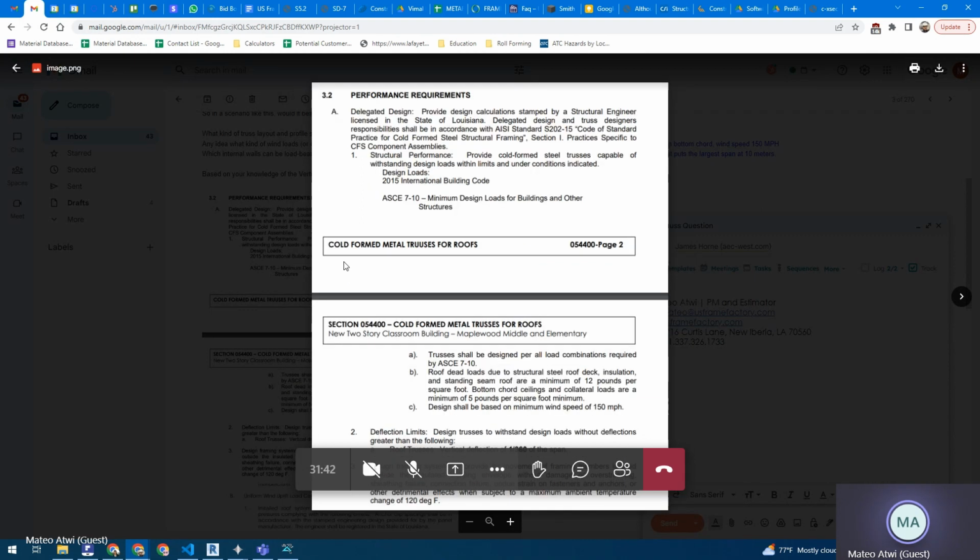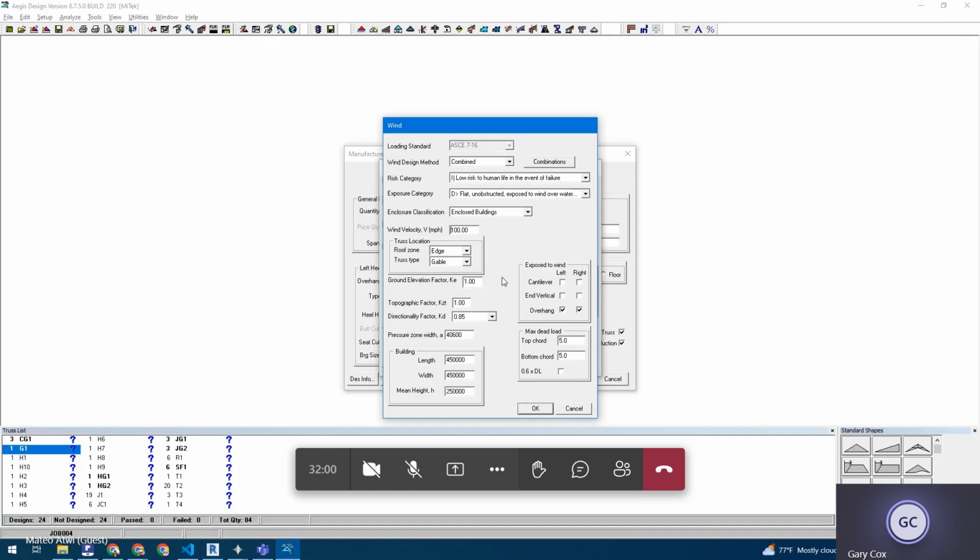So that is roof trusses, vertical deflection of L over 360 of the span. Which is okay, but you'll have to change that. Okay, so wind speed is 150 here. Yep. And that particular one is using IBC 2015 also. Oh, okay. But you can fix that.